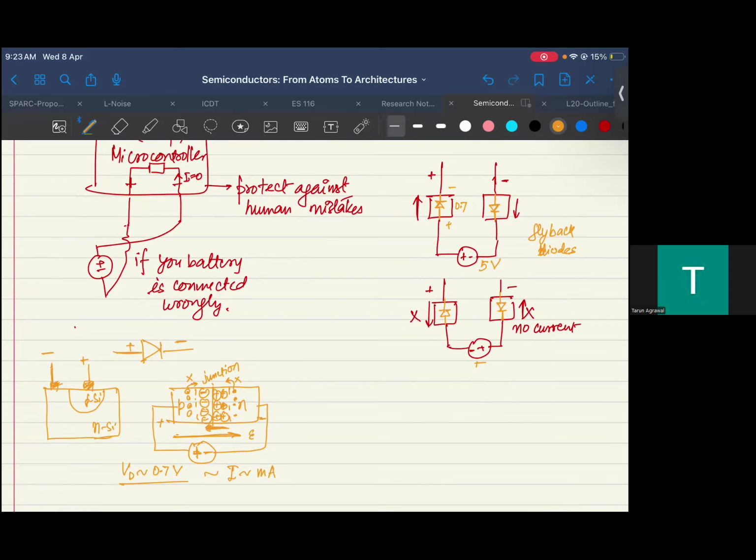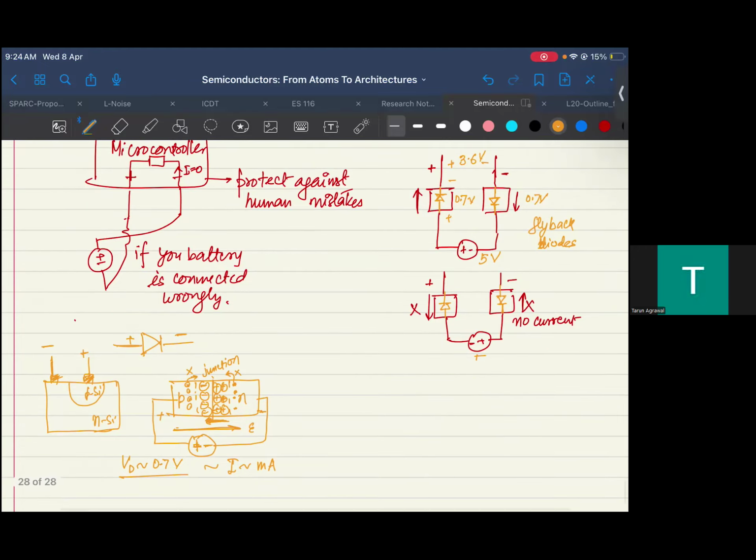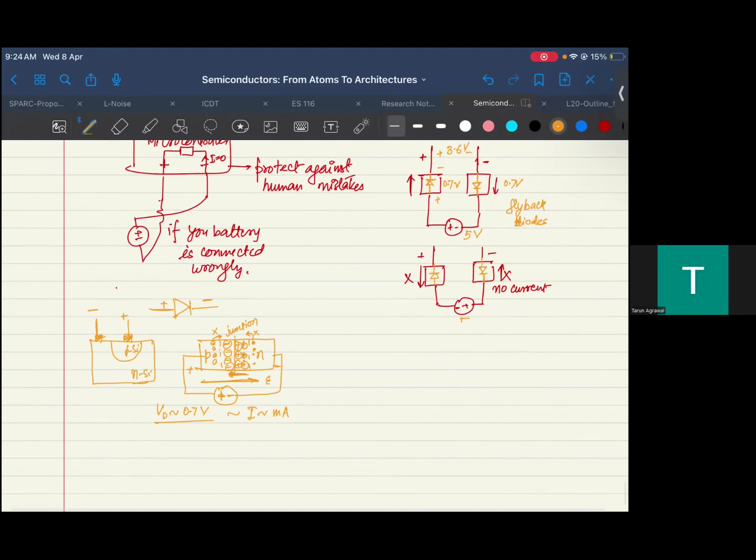Whatever my microcontroller is getting is just 5 minus 1.4, so that is just 3.6 volt between the two terminals. This does not seem like a good device to even go for if I am having such a drop. So is there something interesting that you can suggest by which I can reduce this barrier?